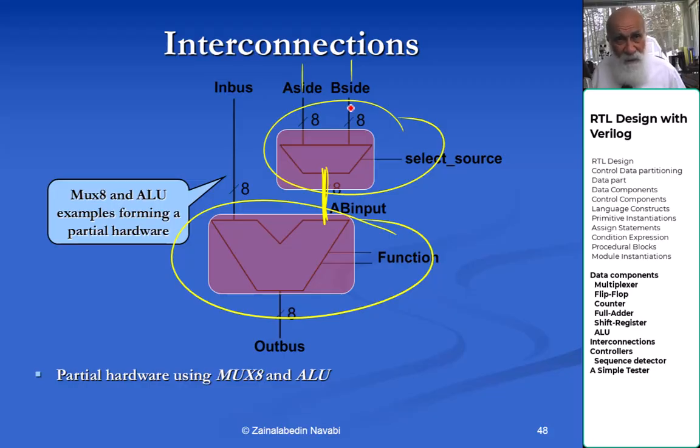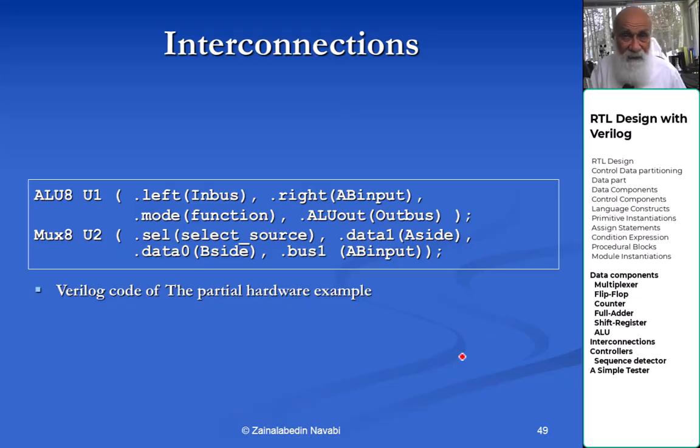I have to declare all of these, and then I use this kind of construct. This is called component instantiation, for instantiating and wiring the two components. Let's read what it says here. It says in bus connects to the left of ALU.